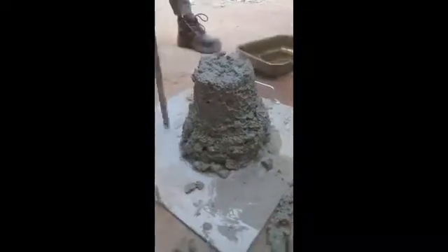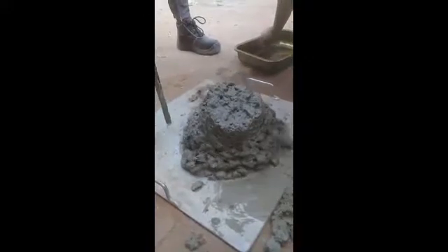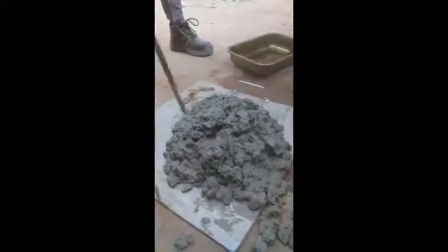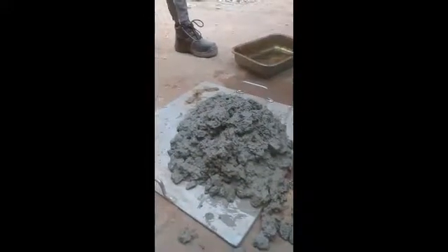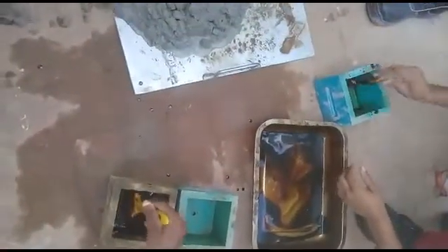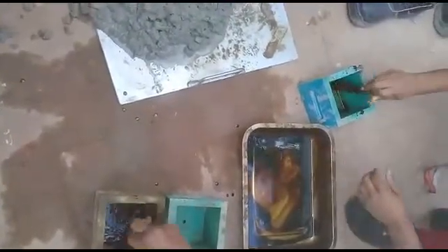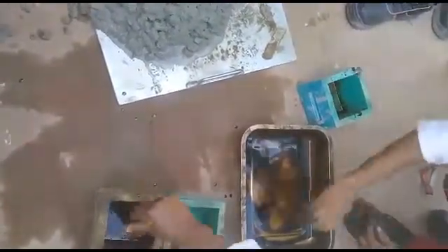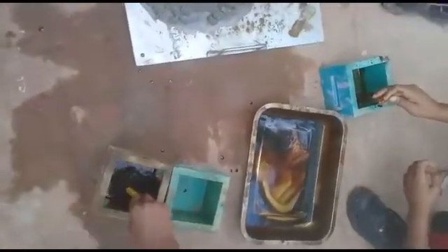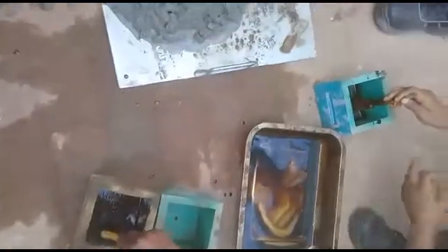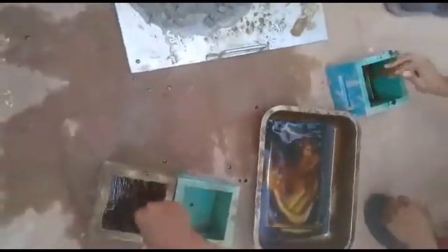Immediately after the slump test, we discussed tapping the non-absorbent board so that the concrete could sag and we would place it in the pouring cubes. Since the slump test was done, the cube molds were then applied with a non-stick material. This material was applied to help ensure that the concrete doesn't stick to the cube mold.